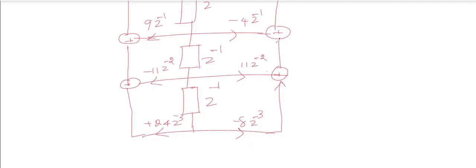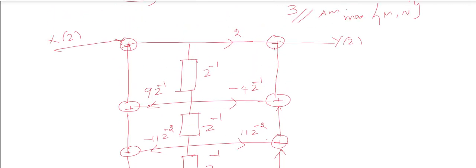So that's the direct form 2 realization. With these two examples you can understand clearly. I hope that you clearly understood the direct form 1 structure and direct form 2 structure implementations of IIR filter. The number of delay elements is 1, 2, 3. Remember that in direct form 2, left hand side coefficients are poles, right hand side coefficients are zeros.